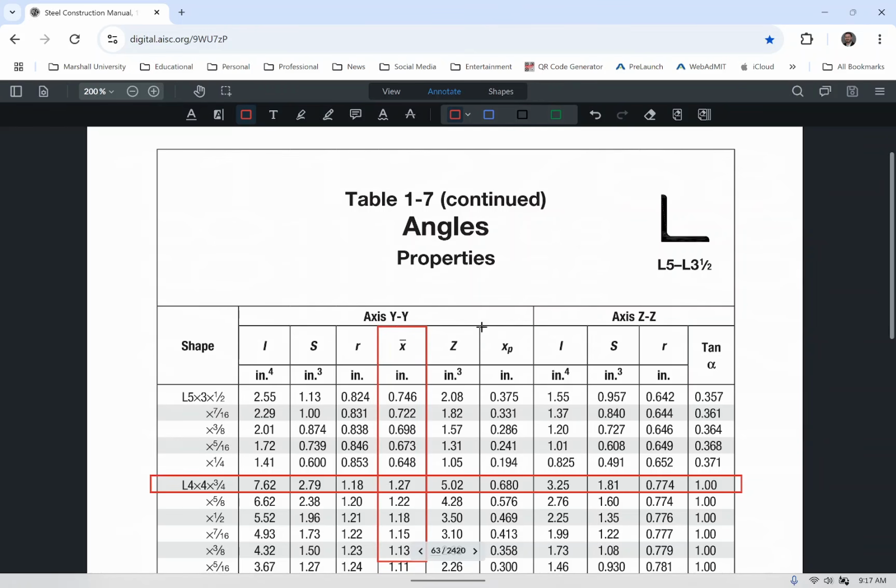But then there's also this term here, okay? I implore you, for tension members, do not use this x sub p. Do not use it, okay? I'm being a little fast and loose right now for what x sub p is. I will explain what it is later.